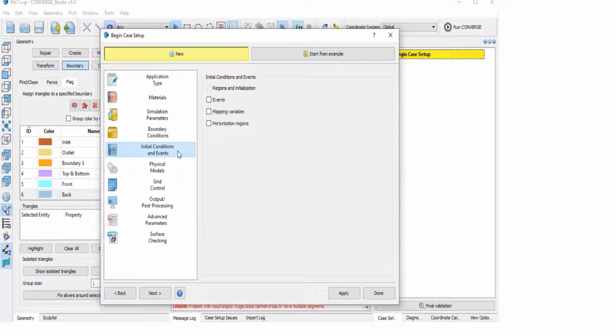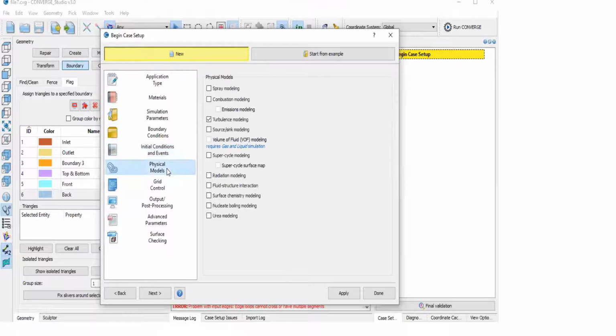You will be marching towards the accurate results, but you will never get a result with zero error, because we are solving numerically and there has to be numerical error. All the solvers are solving partial differential equations at the back end, right? They need initial conditions because they are going to solve this numerically, and to solve anything numerically you definitely need initial conditions.